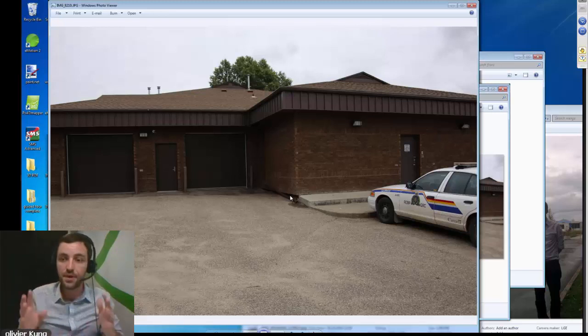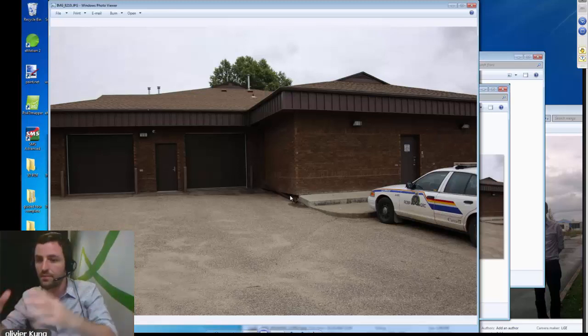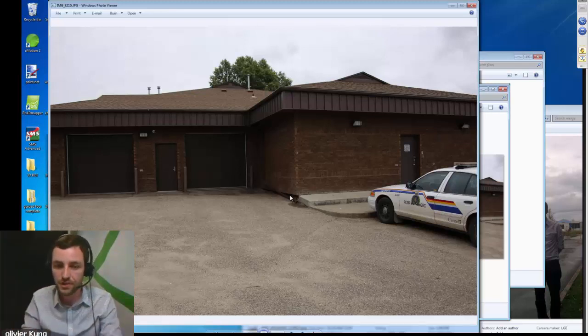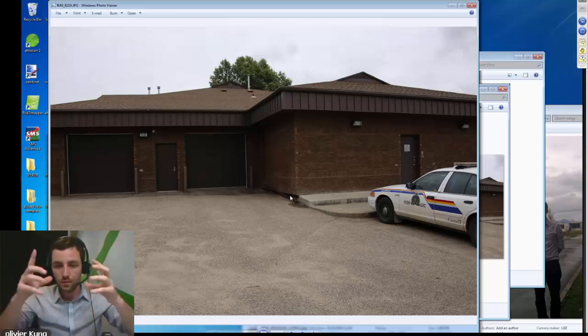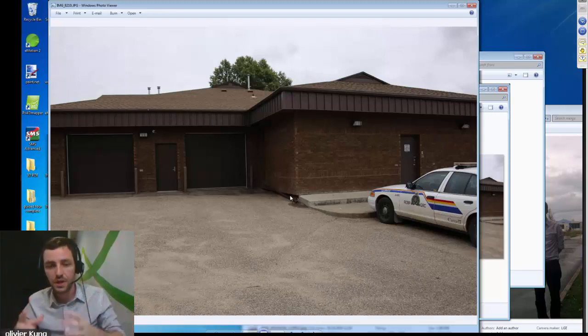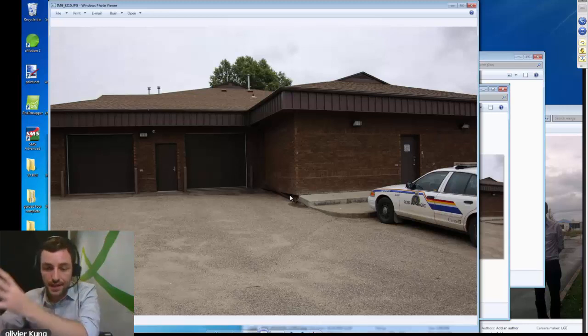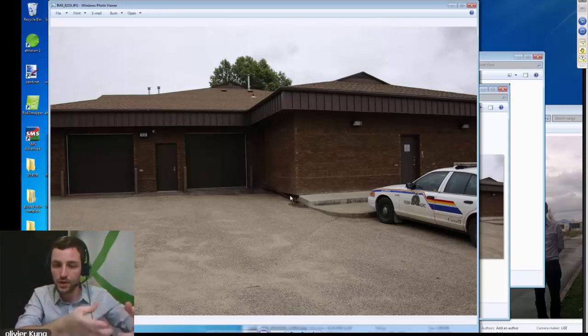It's not very intuitive, but you are adding more mistakes by not moving than by actually moving 1 meter or so between each picture. So whenever you press the button to take a picture, always be translating, moving the camera, and not only doing a rotation.